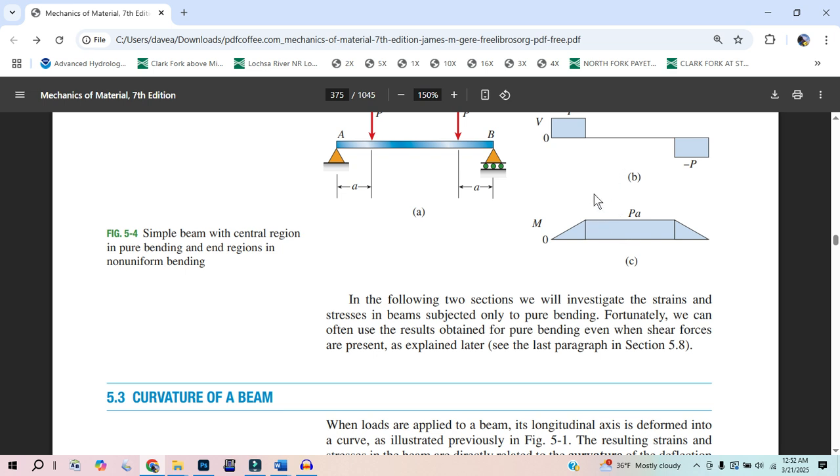It's actually axial tension that rips things apart in pure shear. So, can I say that one more time? If you have compression, things sometimes will fail in shear, due to the compressive loads being too high. It failed in compression, but in a way that it was at a plane of shear.